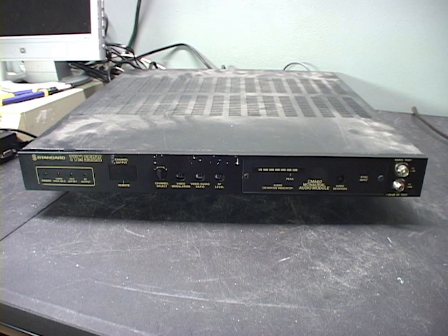They would use a cable demodulator, which is basically one of these but backwards, to receive that over-the-air signal and then demodulate it into composite video, and then they would send that composite video into a cable modulator, and the purpose of that modulator was to distribute that signal throughout a local cable network within that building, and any TV hooked up to that cable jack in any room could pick up the channel with perfect signal quality because it was all coming from a central antenna rather than each TV having to try and pick it up with its own antenna.